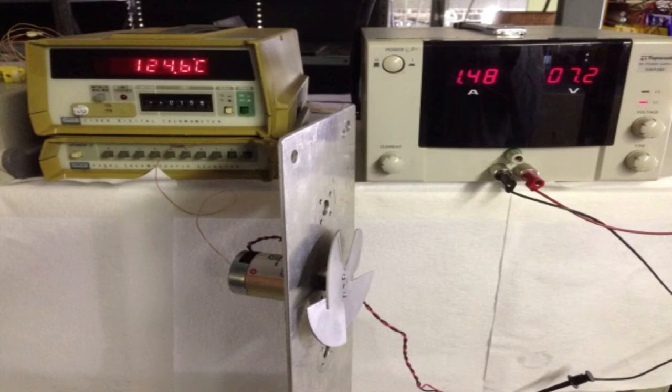Once the motor is mounted to a plate, additional heat transfer will occur. Most of the heat is conducted through the mounting contact between the motor and plate. You can see this reduced the internal winding temperature by 25.6°C.